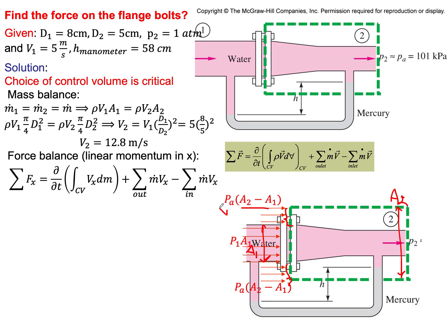So there you go. And then on this other side, we have the water pressure, which is P2, equal to P atmospheric, as you've seen here. That's what's given as part of the problem, acting on the water side. It's compressive and perpendicular. And then you have the air here also contributing with the same pressure. So over the whole area A2, I have P atmospheric acting on it. So P atmospheric times area A2. Okay, so that's the pressure force.